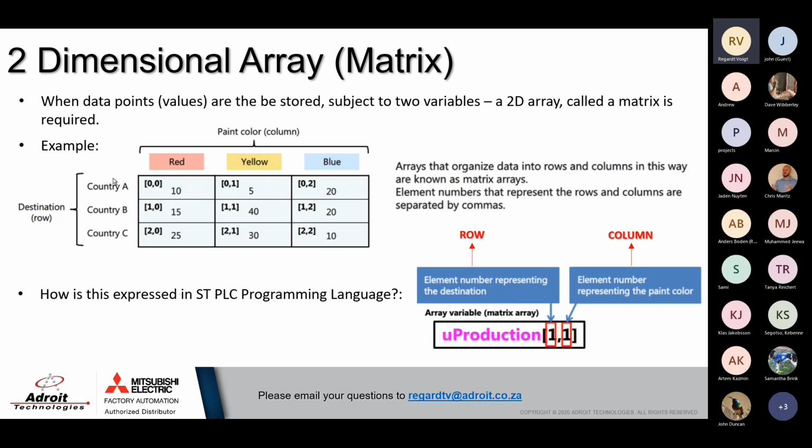So yeah, sometimes depending on your process, you don't want the PLC to handle too much of these processes. So then you share the process with a SCADA. Sometimes it's done exclusively in the PLC. Sometimes it is done exclusively in a SCADA, depending on the application. Okay, so this is an important concept to understand.